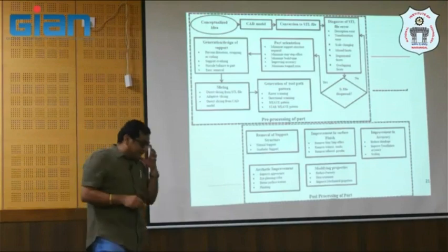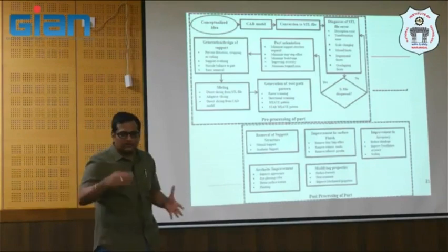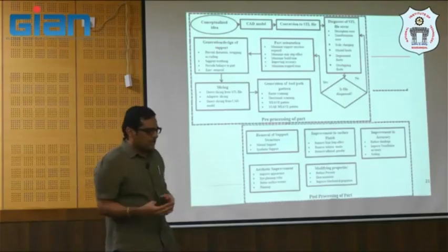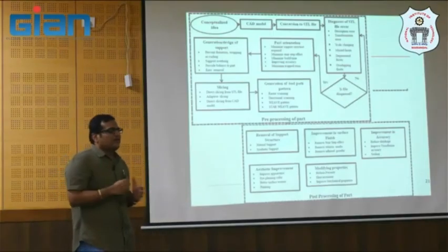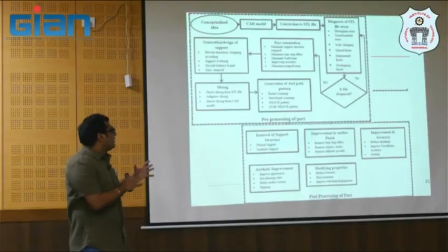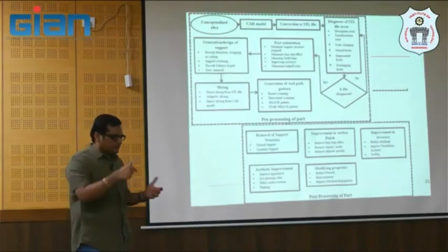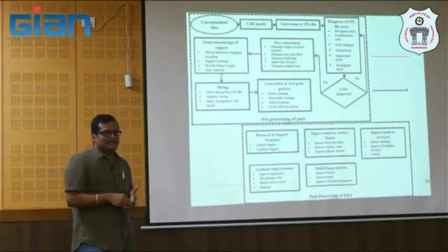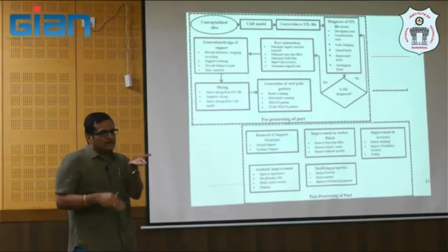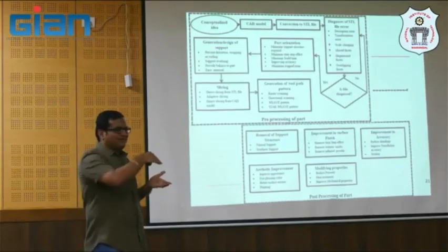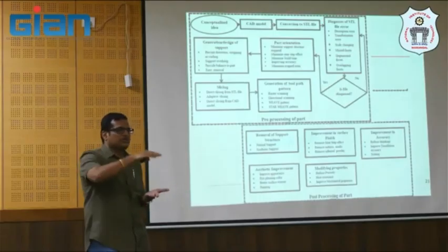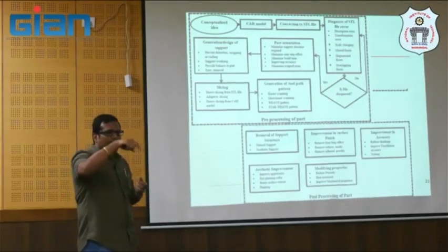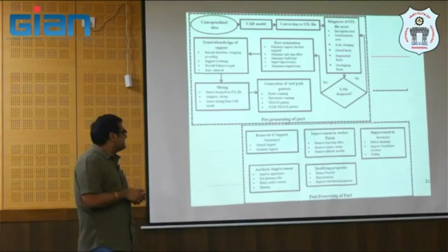It is going to dictate your residual stresses also, which we are going to see in the upcoming days, like how you can minimize those residual stresses. You can do this by manipulating your scan strategies. You may have some angle so that you are not allowing the residual stresses in the same plane or same layer, so you are trying to manipulate your laser strategies.